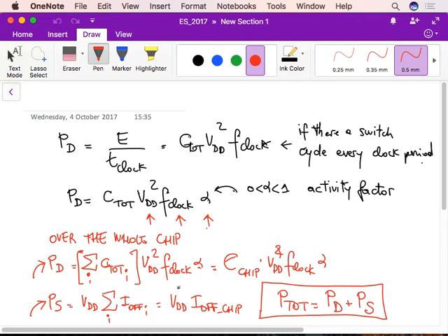When you have done this increase in mobility, you have to keep this deformation, this strain on the silicon in the channel, because otherwise you don't know how to improve performance in other ways. But if you look at these two expressions, the expressions for the power consumption and the expressions for the propagation delay, you can explain most of what has changed in the various technology generations in the last years.